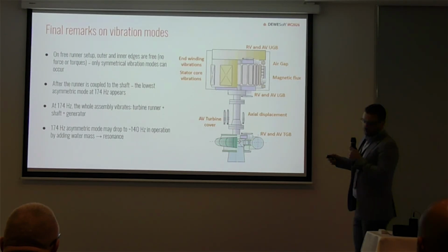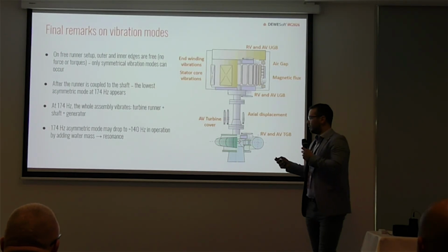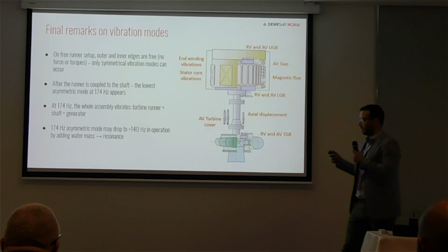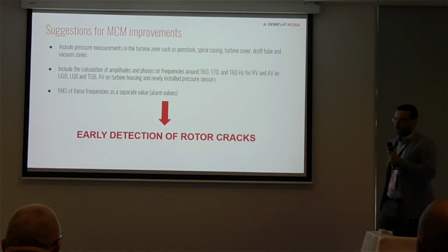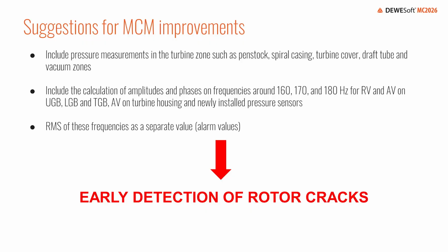So this is actually what happened in operation, and this could be quite the reason why the whole unit is in a resonance. Okay, then if we now concluded there's a problem, the design is like it is, 7 runner blades cause you have excitation at 140 Hertz, and there's a natural frequency close to that, so there's resonance.